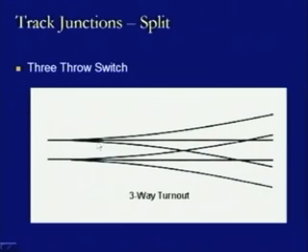So, it means we are supposed to provide 2 tongue rails at this location. Similarly, we have to provide 2 tongue rails at this location, then only we can define whether the train will be going straight or will be coming to this one with respect to this particular lead rail. Because if there is a wheel on this lead rail and if the connectivity of this one is having a throw of switch, whereas this is being connected to this one, then it will go on the main track. Whereas, if this is also being connected and the other one also, then for this curved track, the train will be coming on this one turnout.